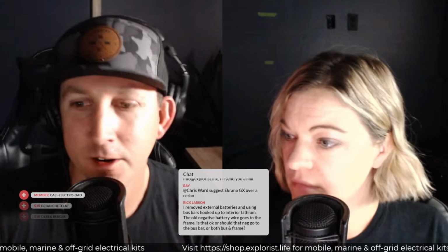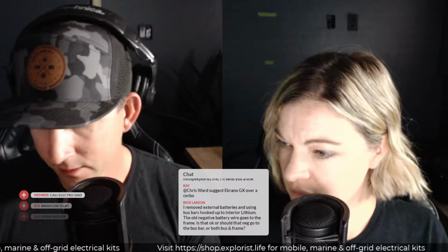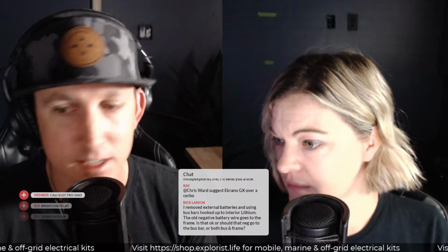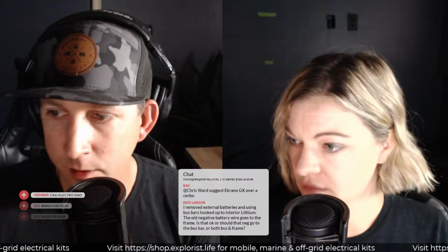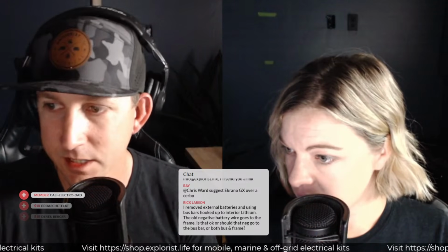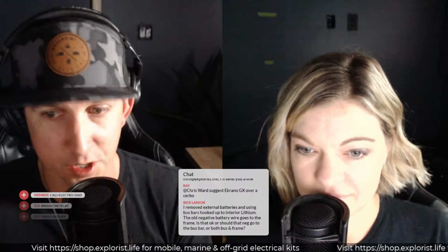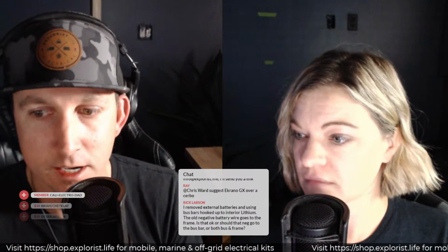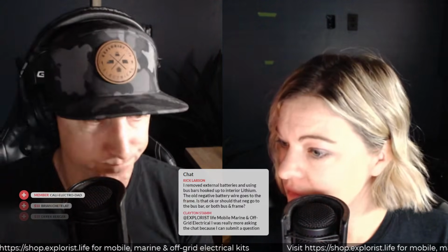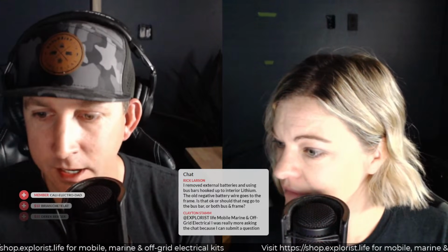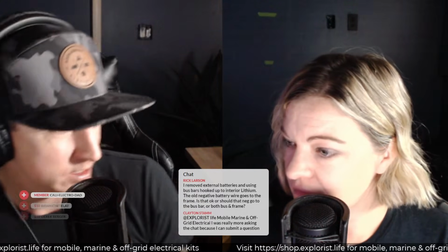we just figure out how many watts it uses whenever it's in use. Okay. Nobody here. So we're going to pretend that this is 20 watts. You can look that up on the data sheet of the Cerbo, and it's running for 24 hours a day, which gives us 480 watt hours. And so you just put in whatever the actual watts of the Cerbo GX is into there. Perfect. Okay. What's the next device?